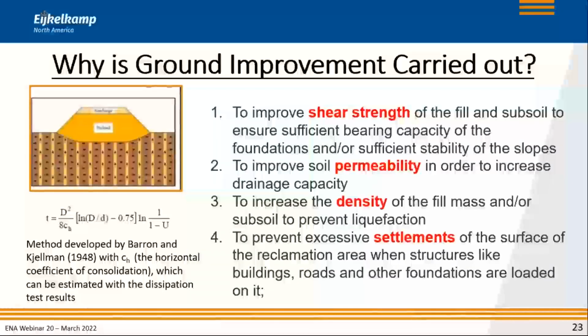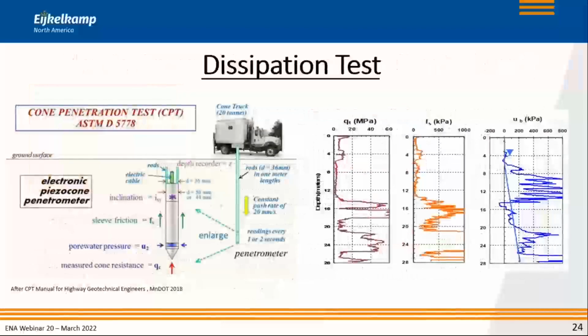And for that, I would like to go back again to the slide that I showed you already earlier, but now focus on, again, the one on the very right, the pore pressure. What we measure during CPT is not necessarily the actual hydrostatic pressure, but the dynamic pore pressure.